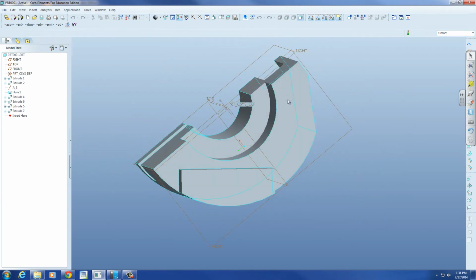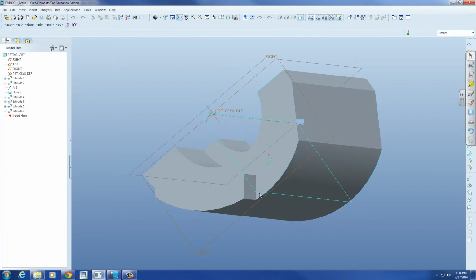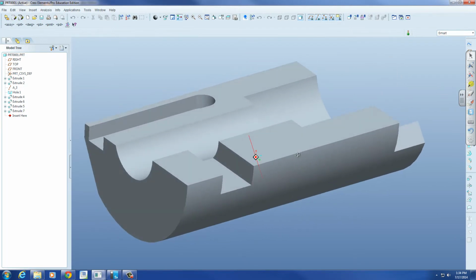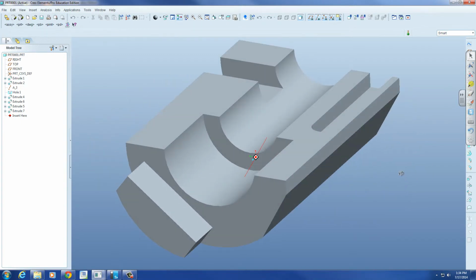If these are so particular that these surfaces need to be here, then we're going to have to core out this side and leave those surfaces. So making this part as a cored out part may be a little bit harder than the draft even on this one. Well, it's not very big. It's going to need to be cored. It's going to need to be hollow.